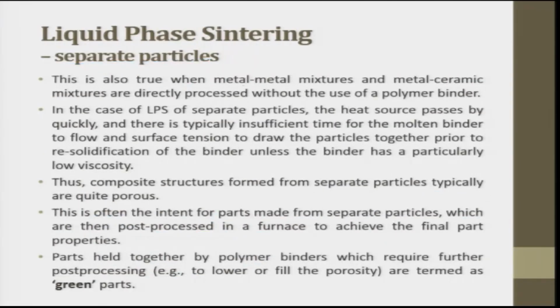This is also true when a metal matrix mixture and a metal ceramic mixture are directly processed without the use of a polymer binder. In this case of LPS of separate particles, the heat source passes by quickly and there is typically insufficient time for the molten binder to flow and surface tension to draw the particles together prior to resolidification of the binder, unless the binder has a particularly low viscosity. Very, very important point.